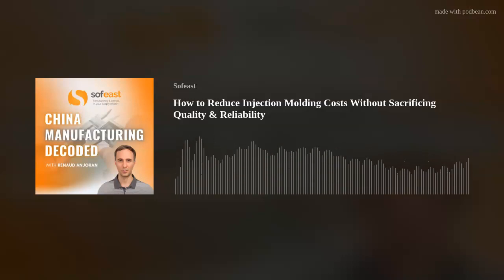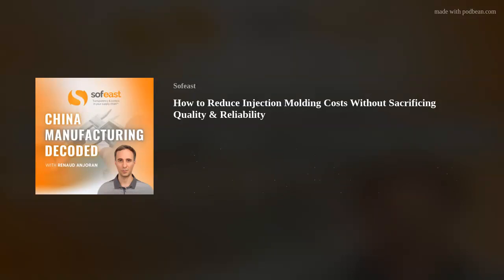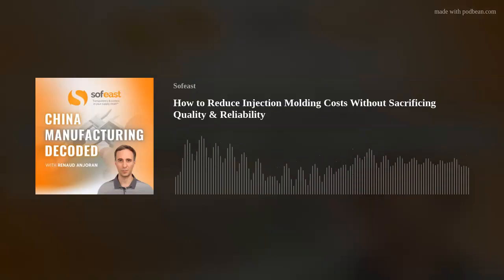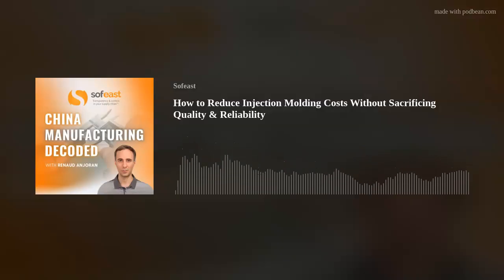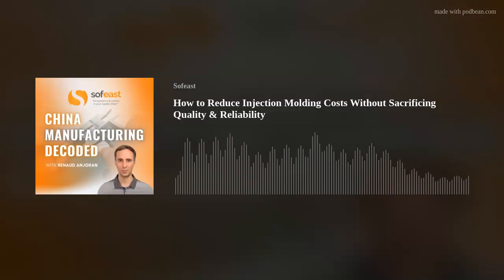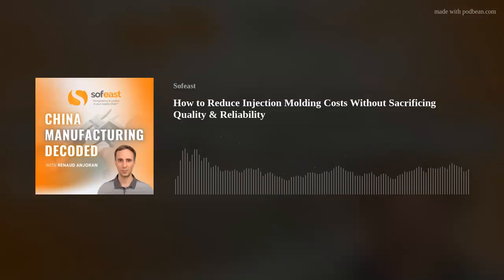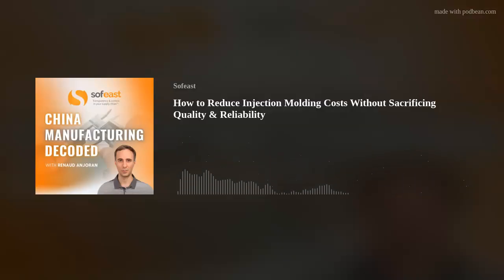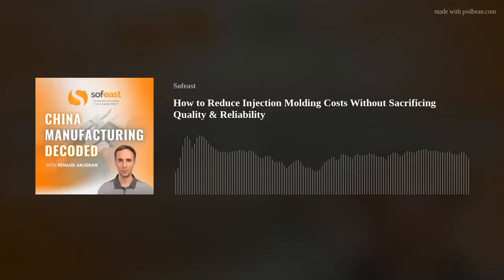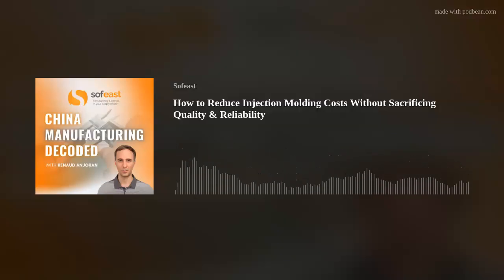which is all about the hot runner and the cold runner. Now, hot runner makes sense because you're not wasting any material between the shots themselves. You've got very minimal sprue waste in the injection process itself versus the cold runner. Again, this is all about being smart from a business point of view.